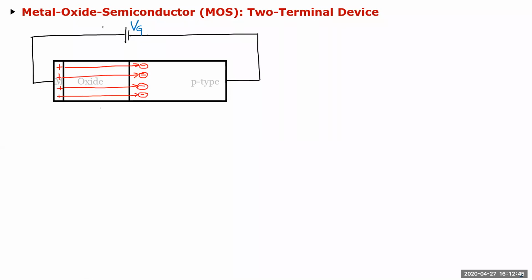because we have a potential difference, some charges will build up. And because we have an oxide, those charges will result in some electric field. And obviously there are no charges in the oxide, so the electric fields will just keep going. When they reach the P-type material, the mobile carriers here are holes, right? So, but it wants electrons. So what it'll do is it'll repel the holes.